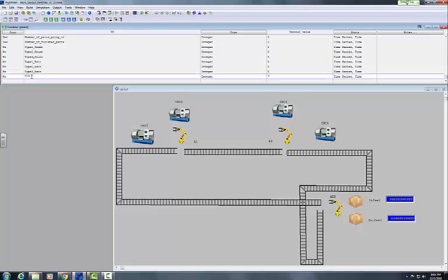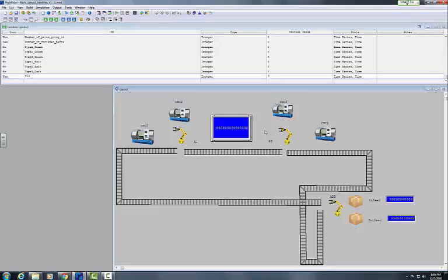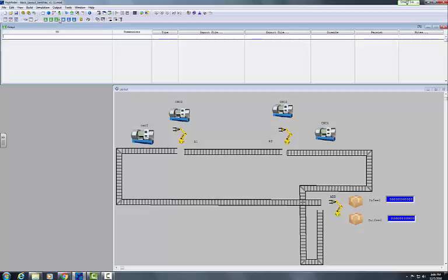And also these are the entries and these are the exits of each one of these entities. And we also keep track of the WIP, or the work in process, so that when the simulation is run for like 100 hours and stopped at the end of 100 hours, there are still some parts which are being handled by the robots. Oops, I kind of created an icon, if you see. Yeah, so what I was trying to say is work in process is basically when you try to stop the simulation in 100 hours, there'll be still some parts within the robots or within the machines or on the conveyors. So in order to keep account of these entities, we have defined variables. Arrays is something which we have not used now.